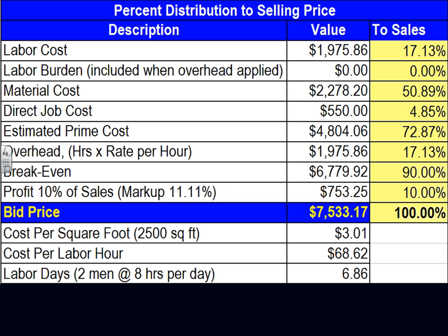Any comments? Any questions? The other one they do is cost per square foot. They take the cost as 2,500. You guys did it with your friend Chad. 2,500 square foot divided by the overall cost of the project. Give me $3. $3 per foot for every house that we have done. And Aaron started taking off the project, and he came up with $1 per square foot. That's a flag. Do you guys see why they use them? You use them as a flag: is the project on track? Should I trust this judgment, or should I go review it?